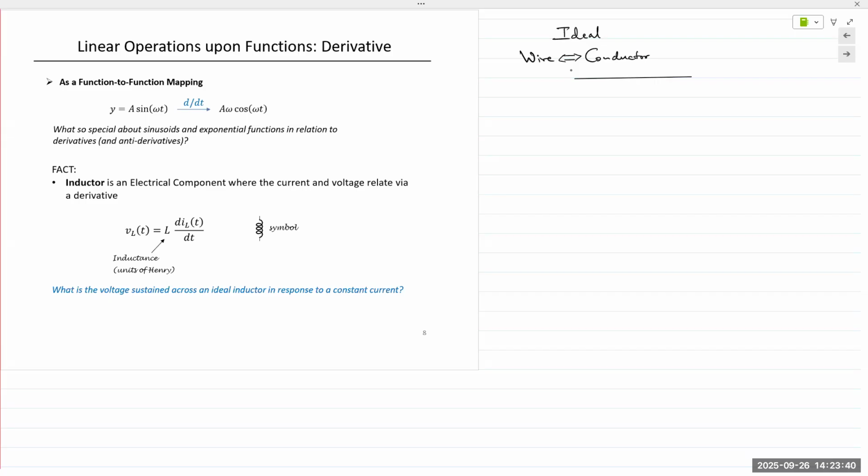So a wire inherently has resistance, it has inductance, and it has capacitance. Resistance is noted with uppercase R. Because we are dealing with circuit theory, all analysis is theoretical, and in theoretical analysis, we consider everything as ideal. But in real life, there is nothing that is ideal, right?